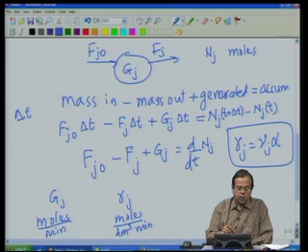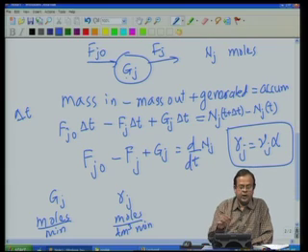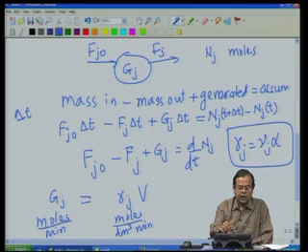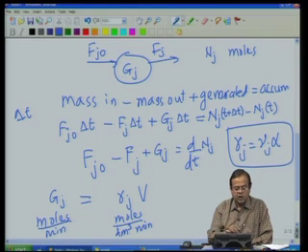So, we have Rj as the rate at which the species J is undergoing reaction, and it is the same throughout the entire volume. If that is the case, then Rj multiplied by the volume of the reactor must be the total rate of generation of species J, that is Gj. So, if there are no spatial variations, then we have Gj equal to Rj into V.